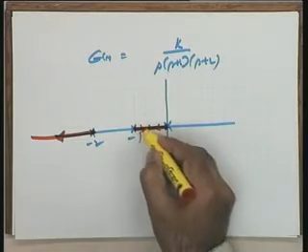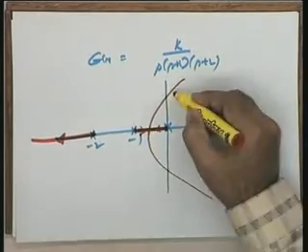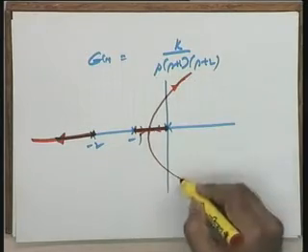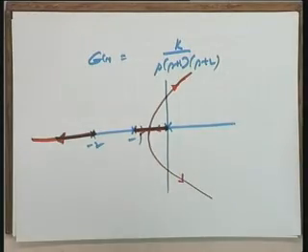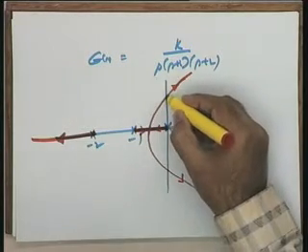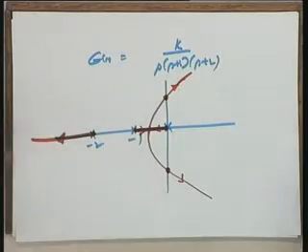So, these are the directions, and therefore, the root locus most appropriately will go this way, that is asymptote, angles, etc. you will determine. The last rule which I want to give you is the following, that you can determine the point of intersection with the imaginary axis using the Routh-Hurwitz criterion.